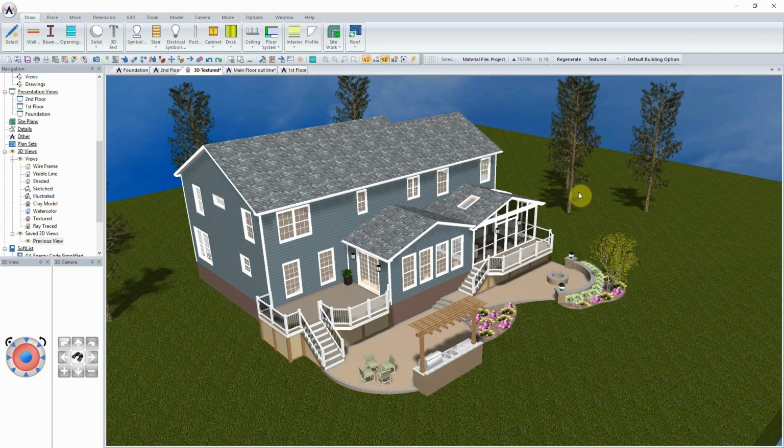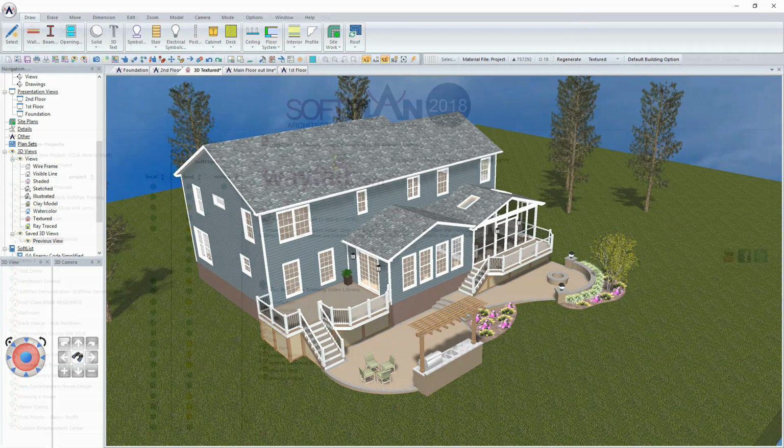Today's class is going to basically revolve around creating a project, what type of walls to use, how to sketch those walls in and set up dimension options that will suit you. We'll add the openings to the existing structure, create both the foundation and the second floor, and get things like the roof in place. With all of that set, then we will be able to begin designing the exterior of the drawing as far as the outdoor living space we're proposing.